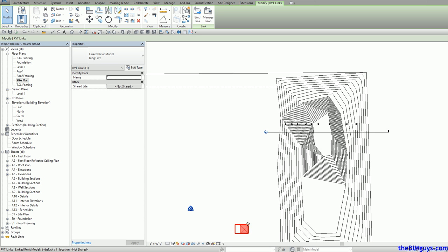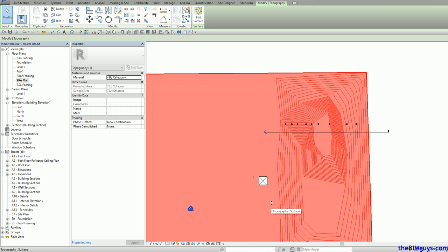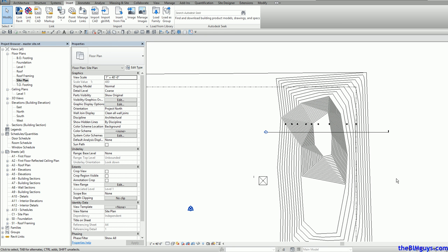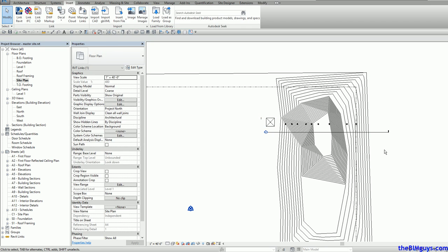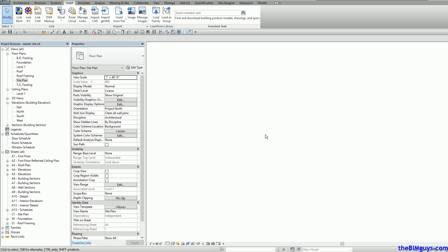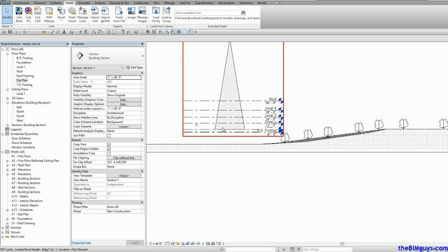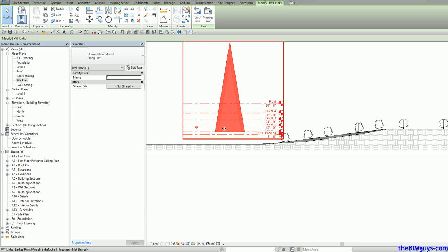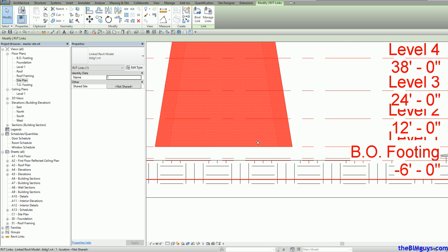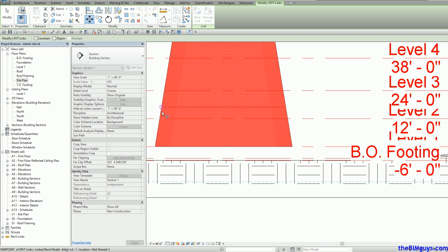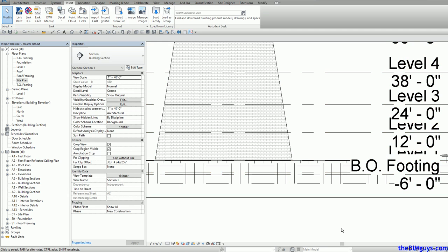Site plan. It might get complicated depending on the elevation, huh? Yeah, what I'd start with is maybe flat right now, but I wanted to show you how I build a site that you wanted to berm up. So if I was to say currently to keep it simple, I'm going to go back to this here, and there it is. Now I want to bring it down. Now we can move it or use arrow keys. You can nudge it. Use arrow keys will make things go up and down, which is quite nice. And I can bring it about where I want it to be, or we can use the move command like AutoCAD. Move from that base point right there, come on down to the ground right there, and now it's sitting dead on the ground.